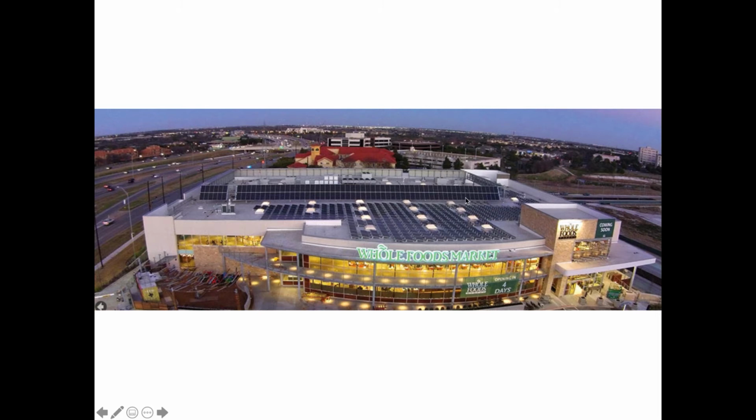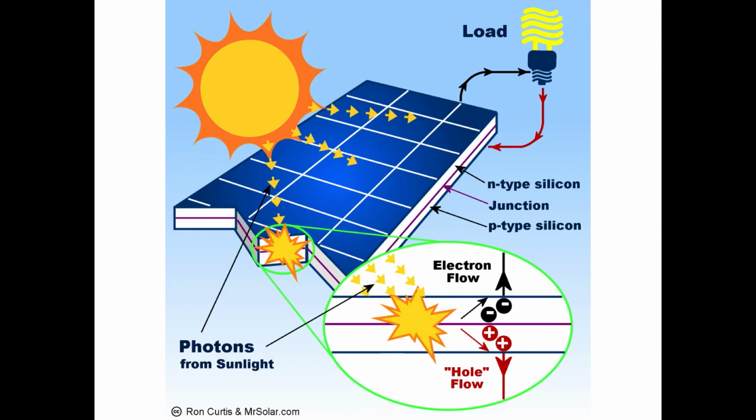and you can see they face in different directions. The solar panels here on the lower part of the photograph are tilted to face east, so they capture morning sunlight through the middle of the day. The solar panels here in the back of the photograph face south, and so during the middle of the day to the late afternoon, they maximize the amount of solar energy that is used.